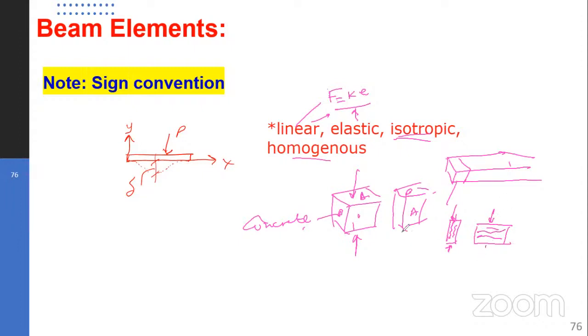And that's why, in the design of timber structures, we always specify whether the stress given is the permissible stress along the grain, across the grain, and so on. So we talk of timber being homogeneous, but it's not isotropic. The characteristics of the material are not uniform in all directions. So that should stick in your mind. We have many materials having that characteristic, where in one direction it is so strong, but in the other direction, which we try not to utilize, maybe it's weaker.